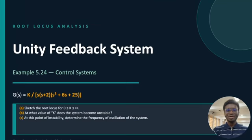Hi everyone, I'm Winnie Charles Inchi of Group 24, and today we are presenting on the root locus analysis of a unity feedback system. Our goal is to sketch the root locus for k, which ranges from 0 to infinity, find the value of k for which the system becomes unstable, and also determine the frequency of oscillation at that value of k.